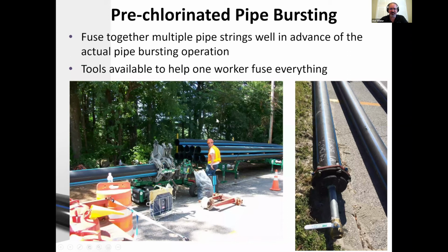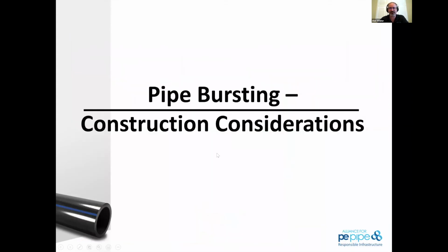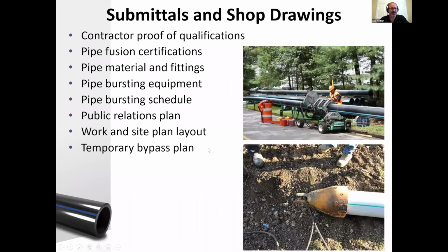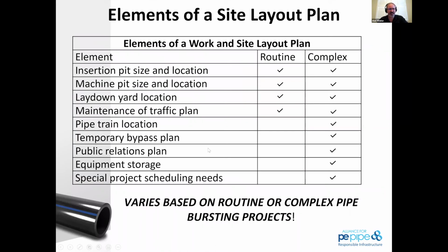We just had a question about excavating the services. Yes, they do need to be excavated because those are hard connections as we go through that. When we look at long-term durability of the pipe, that is important to be able to make sure we have the hard connection either through mechanical service connections, electrofusion, or other mechanisms of fusion to be able to pull it through. So I'm going to skip through this one of shop drawing submittals, Matt, and then get right into a site layout plan if you want to talk about that for a second.